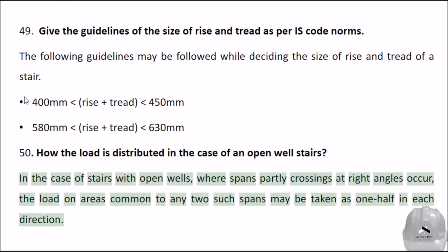50. How is the load distributed in the case of open well stairs? In the case of stairs with open wells, where spans partly crossing at right angles occur, the load on areas common to any two such spans may be taken as 1/2 in each direction.